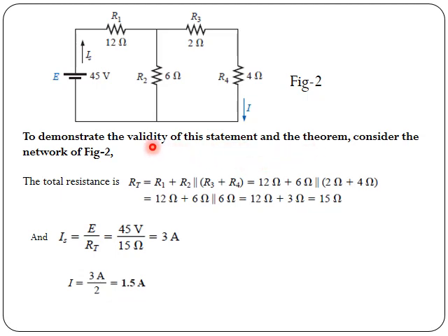Firstly, we need to find the total resistance as seen from the voltage source side. You can see this will be a series combination of R3 and R4, then that in parallel with R2, then that combination in parallel with R1 will contribute the total resistance.